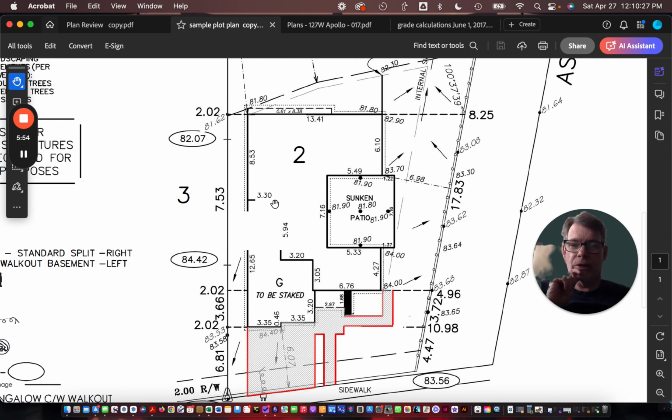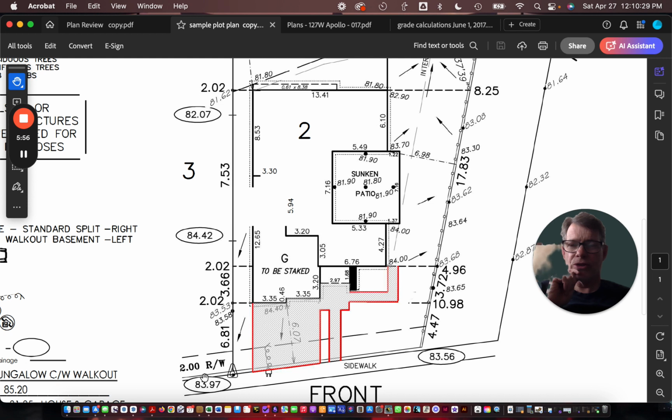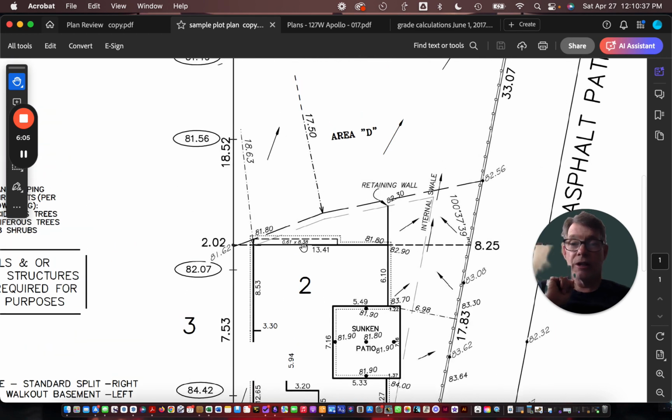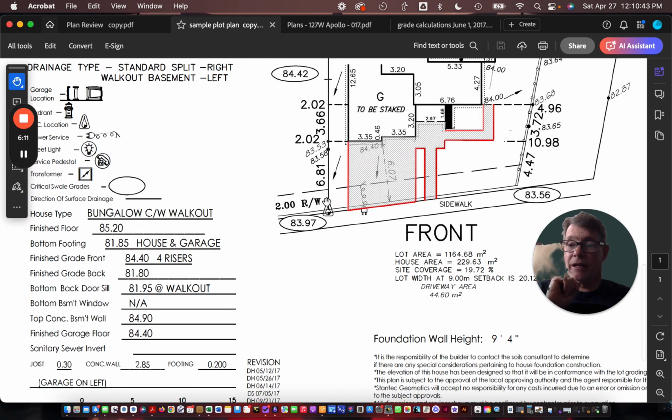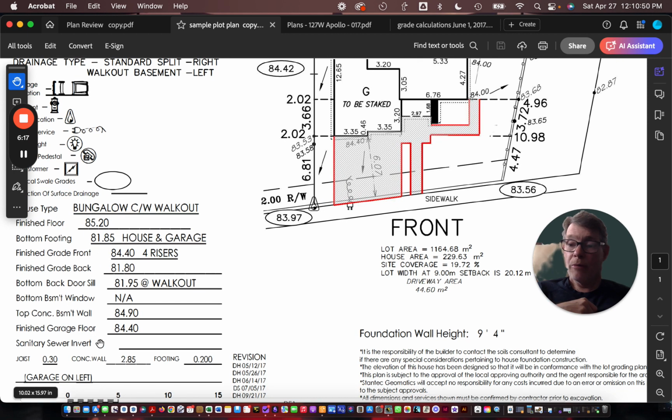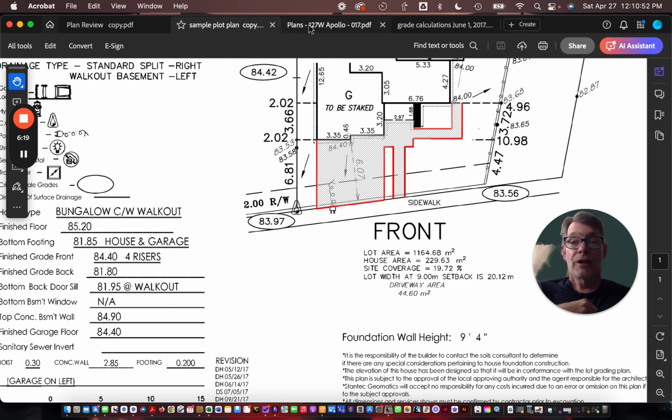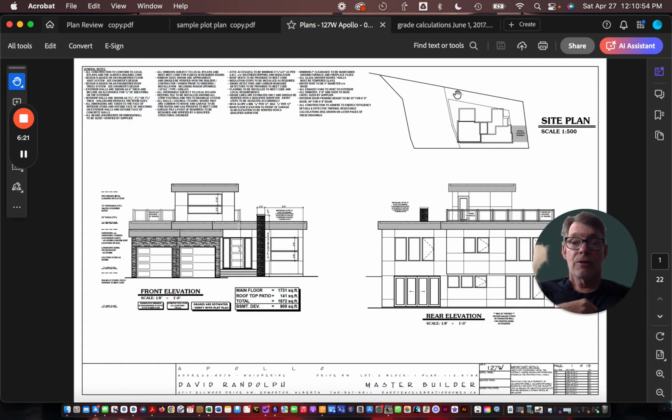And so in this particular neighborhood, what we have to do is take a look at things like, we basically are asked to take an average of these four corners, what their heights are, and then analyze the height of the building. And we may have that information on the plot plan, or we might have to look to the actual drawings, which we'll just skip to.